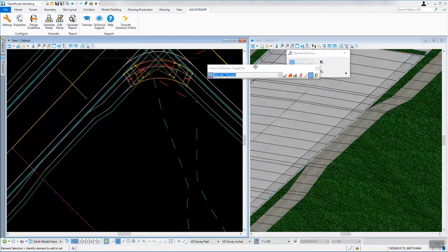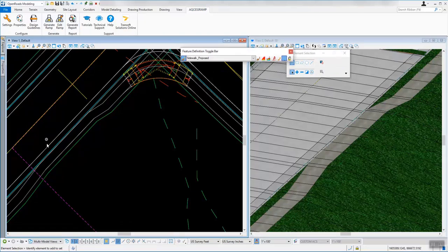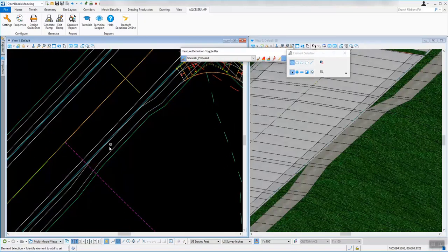So what I've done is I've got this roadway out here that has curb information on it, and elevations are based on the corridor. Also in that corridor we have a sidewalk, and I've done a small area right here where I've done a parametric constraint. We've got a normal sidewalk coming in, and I want the sidewalk to meet up with the curb here and then come back out, so I've got a little parametric constraint in there to allow us to put in our curb ramp through this section. Okay, so I do have a couple of lines drawn out here.